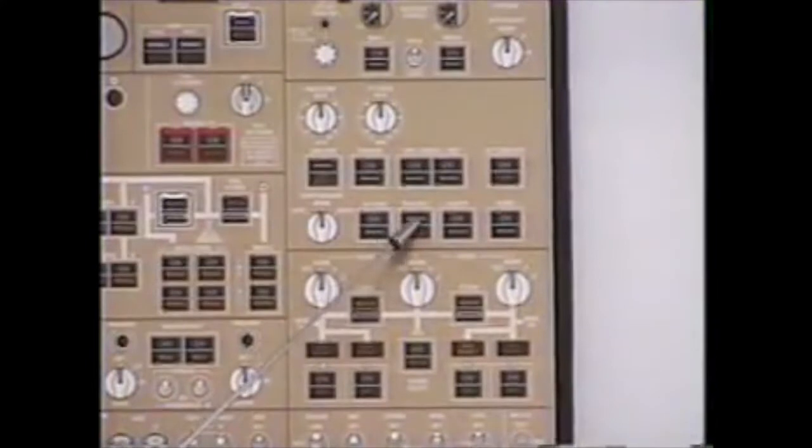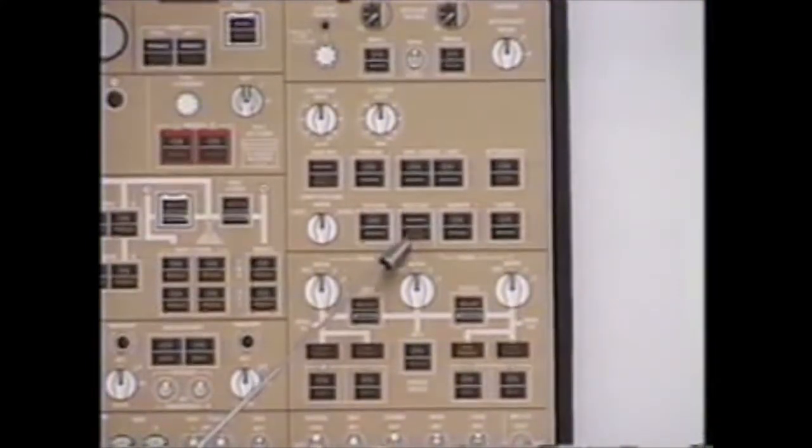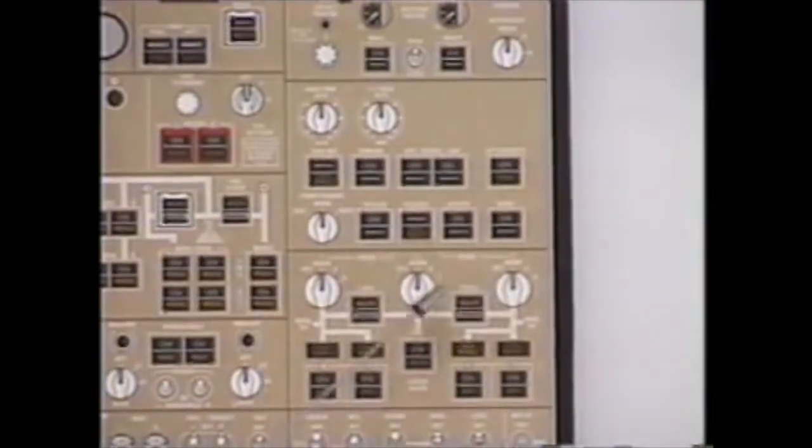Note in the pack reset switch we have a sys fault light which will illuminate if an air conditioning pack trips off due to a pack fault. Each pack has the ability to trip due to a pack fault, individual of each other. In addition to a pack fault, pressing a cargo fire arming button for the lower compartments forward or aft will shut down pack 3. In addition to a pack fault, overpressurization on your airplane will trip pack 2.